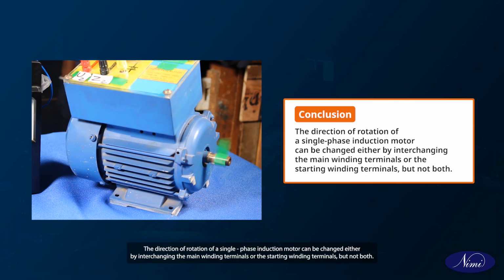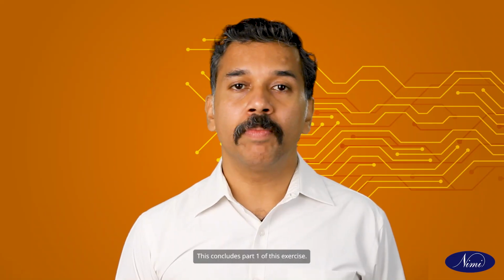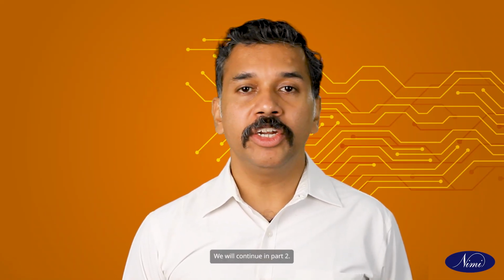Conclusion: the direction of rotation of a single-phase induction motor can be changed either by interchanging the main winding terminals or the starting winding terminals, but not both. This concludes part 1 of this exercise. We will continue in part 2.